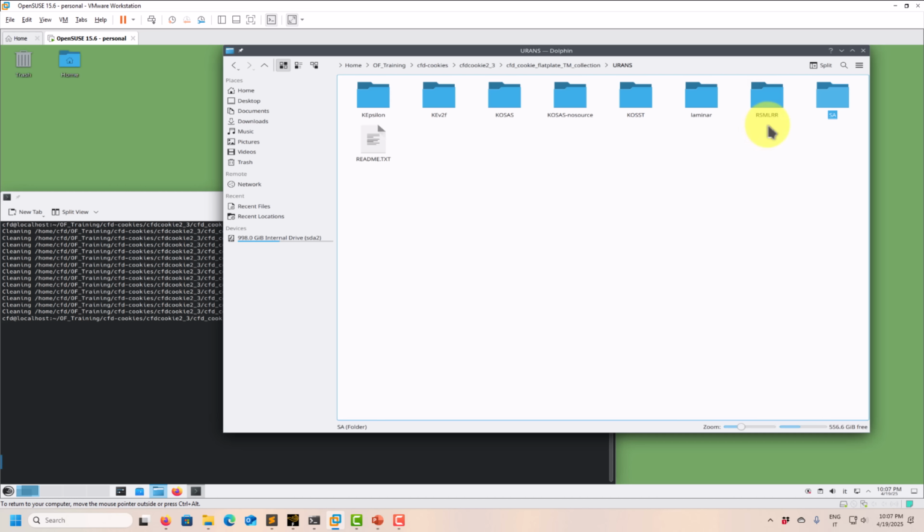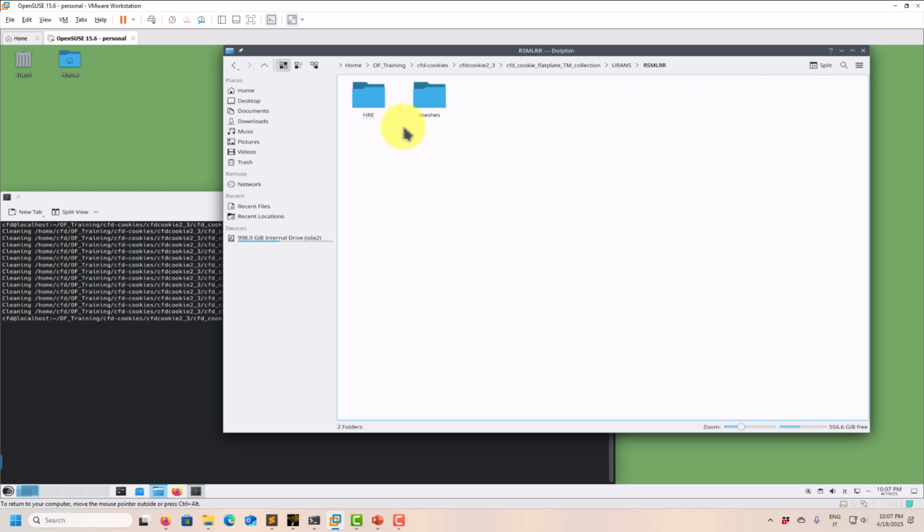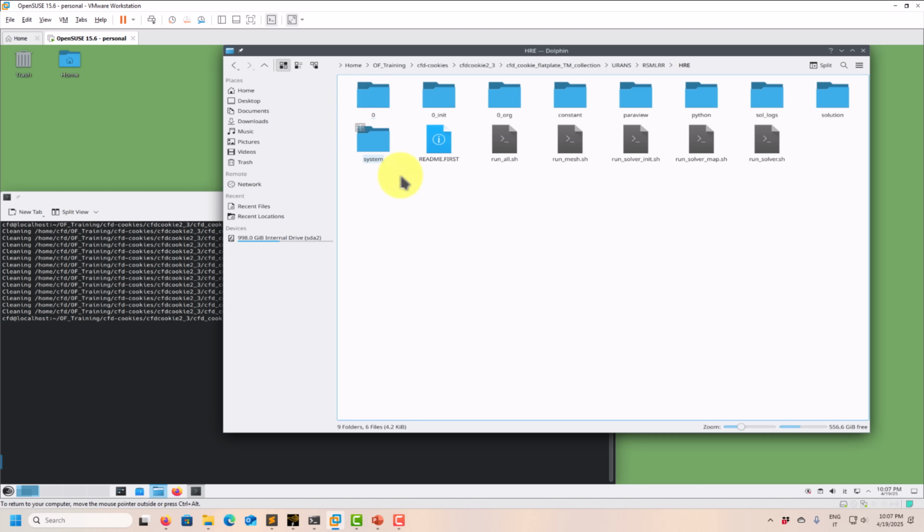Okay, so finally, let's talk about this one. Reynolds stress, the LRR. This is the formulation I like. This one, remember, you only have it in the flavor of HRE. And this is a very interesting model. Okay, as I say, these are extremely difficult to make converge, steady or unsteady. Very difficult. And actually, I think I didn't manage to get these models to 100. They were for some reason always crashing, and I didn't want to spend too much time trying to stabilize.